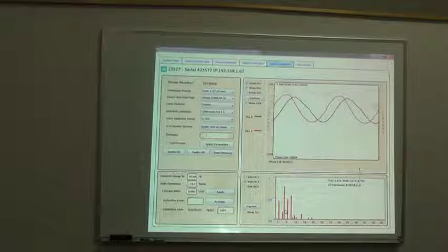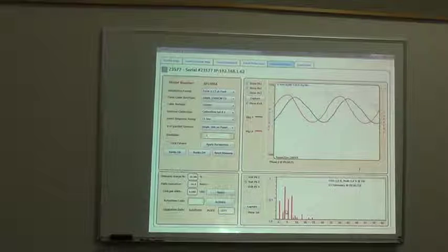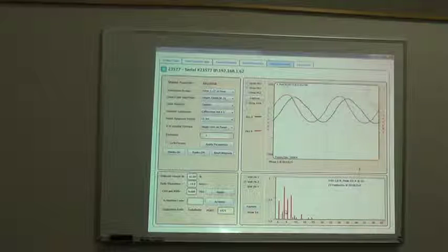The reason was because there was very little load. The loads are causing it. That's affected by what goes on in the building and what the utility's delivering to you in terms of the voltage. In other words, if you disconnected the building from the grid and measured the voltage distortion, you would see what your baseline voltage quality is. Everybody else has got the same problem, so they're crapping the voltage out back at the substation, and that's getting spread to everybody.